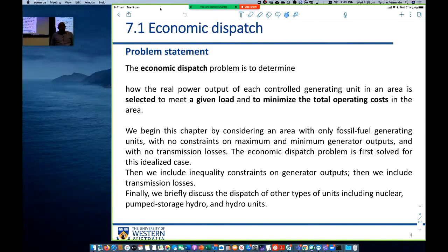Base load are generators that we don't stop; they will be working continuously. Examples of base load can be coal power plants, where it used to be cheap to produce electricity because coal can be cheap. Then nuclear power plants, even though the setup cost is high, the fuel is cheaper, so it can be used as a base power plant.